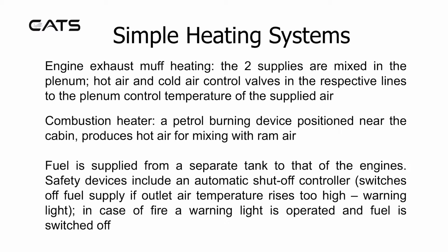Engine exhaust muff heating: the two supplies are mixed in the plenum. Hot air and cold air control valves in the respective lines to the plenum control the temperature of the supplied air. Combustion heater: a petrol burning device is positioned near the cabin. It produces hot air for mixing with ram air.